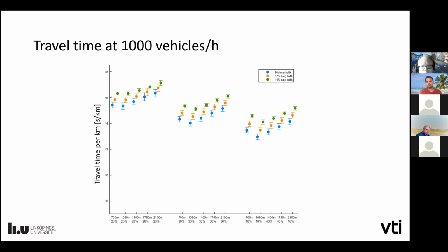But this is of course a very hypothetical scenario, because here we don't have any intersections and so on. There might be lots of different reasons why you choose a certain length, due to how the road goes, the distance between intersections, and where you have an uphill, because you would prefer to have 2 lanes in the uphill direction at that point. So it's not always that you can choose.